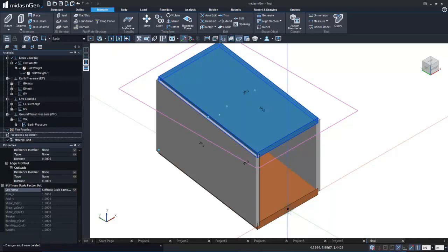Alright, we have got another question about how to model staircase. Well, to model the staircase, we can make use of the inclined slabs itself. We do not have predefined staircases as such, which can be directly inputted in the model. But you can actually have your staircases modeled as slabs itself. So those can be inclined slabs. You can have incorporation of intermediate landings and beams, and you can perform the analysis and design the same with the help of loading.